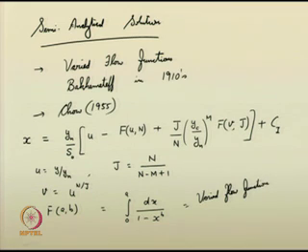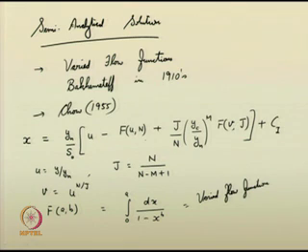The tabular values of these varied flow functions are available in the literature, especially in Ven Te Chow's book on open channel hydraulics, where you will get varied flow functions for different parameters. You can directly substitute them. So, this is a semi-analytical approach, and one can use it for solving the gradually varied flow problem.